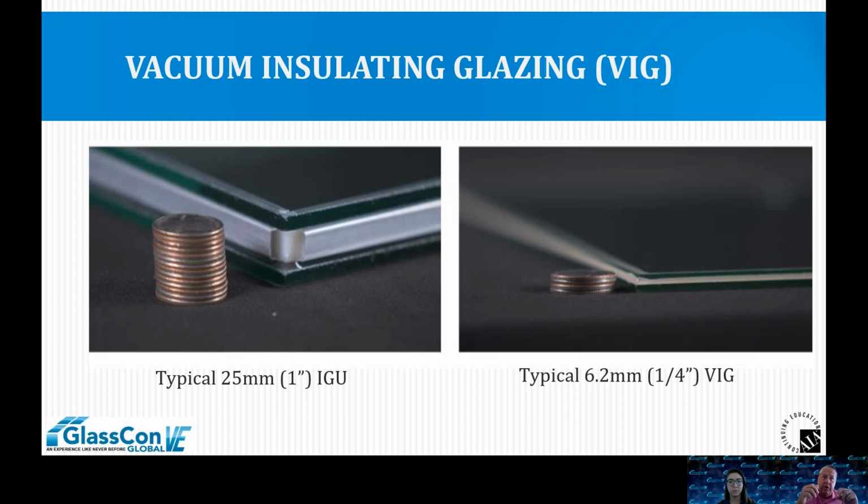So just as a very brief overview, a regular IGU is two pieces of glass. Typically you have a low E on surface 2, and you have a 1/2 inch to 3/4 of an inch air or argon or some sort of gas to give you the insulating property values. And VIG essentially is the same two pieces of glass, but instead of an airspace in between, it's a partial vacuum in between. And the reason is a vacuum is a very good insulator, so you can get some high performance properties with that. So that's what we'll be talking about today.